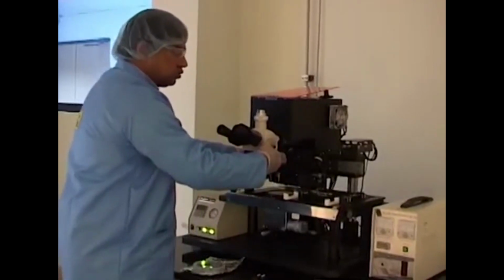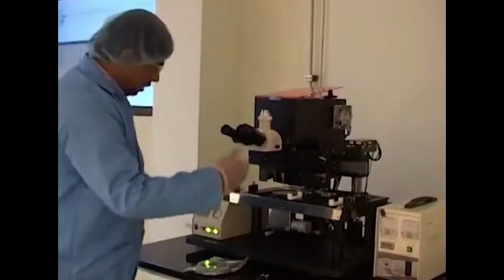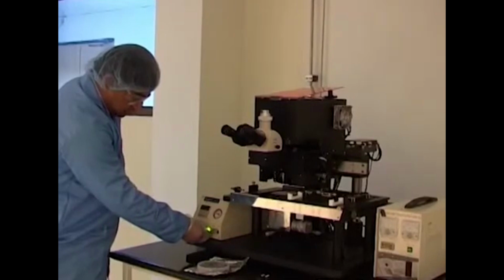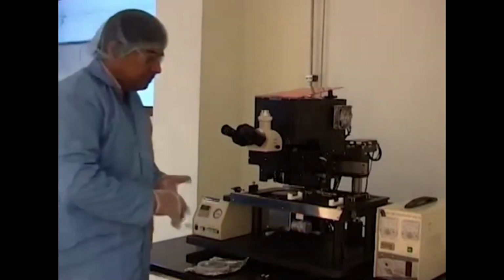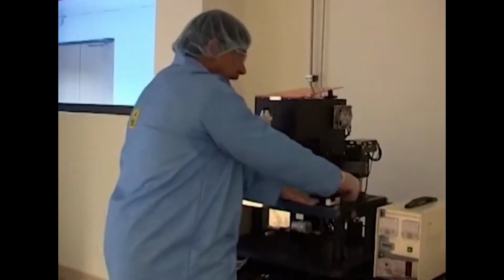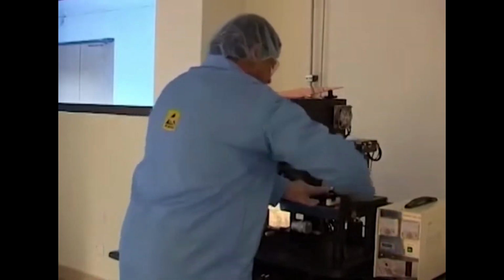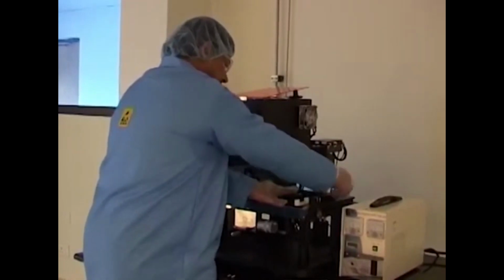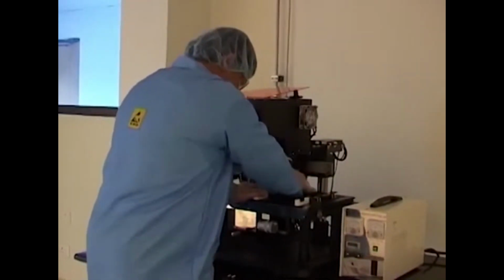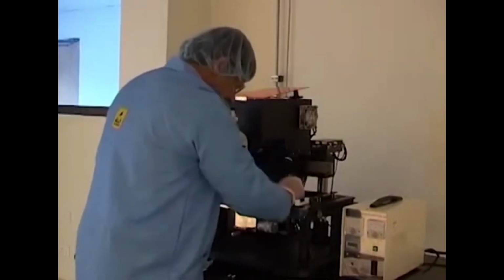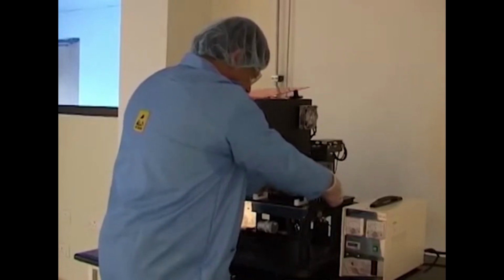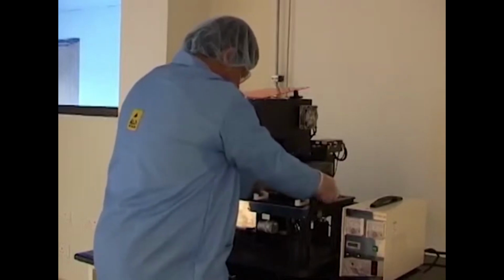Here, we also need to reverse the sequence to pull out the mask. We need to switch off the wafer holder as well as the mask vacuum, and pull back the mask in a pretty much similar manner as we had loaded it before. Okay? These bolts need to be untied so that they lose grip on the top of this wafer holder. Slowly move the holder back in its place.